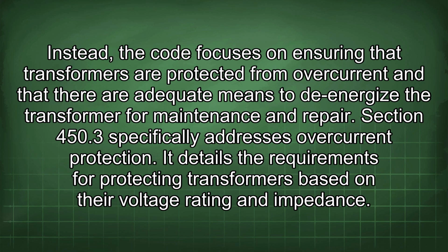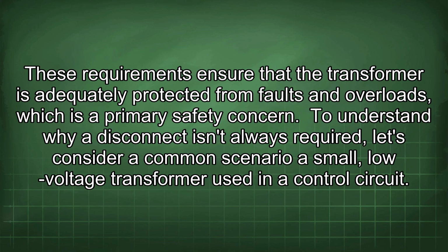Section 450.3 specifically addresses overcurrent protection. It details the requirements for protecting transformers based on their voltage rating and impedance. These requirements ensure that the transformer is adequately protected from faults and overloads, which is a primary safety concern.